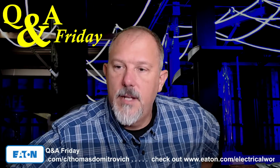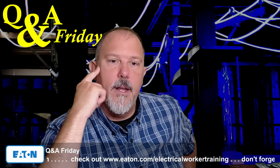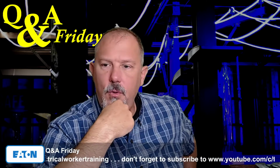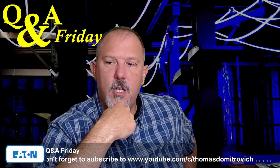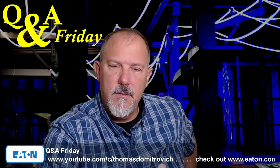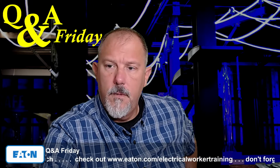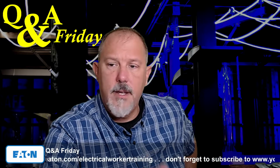If you hardwire it to an enclosed GFCI breaker, then no GFCI protection is provided for the outlet. If you have an enclosed GFCI circuit breaker, it's a listed product. So it's no longer an outlet, right?